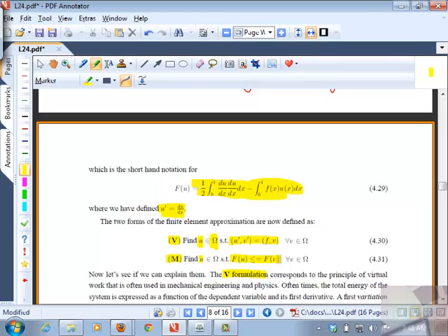So when we say the functional is minimized, one of the ideas here is that you are expressing the functional as some representation of the energy of the system. And so you know that the energy should go to the minimum for an equilibrium point, for a stable point. So you try to minimize this functional F. Think of it like this. As an engineer, I have different functions in my toolbox, and I take each one of these functions and plug it into the functional and evaluate the functional. I get a number, because it's all integral.